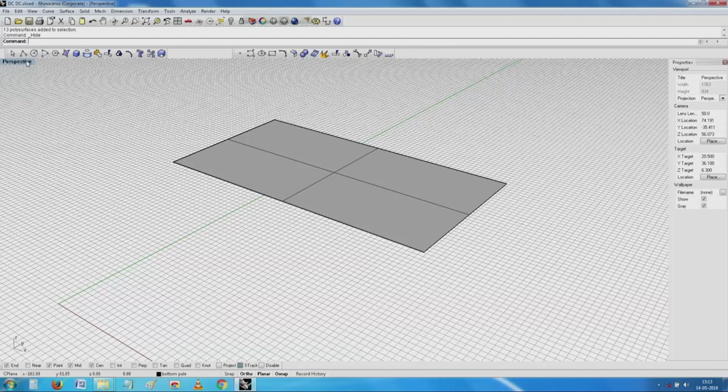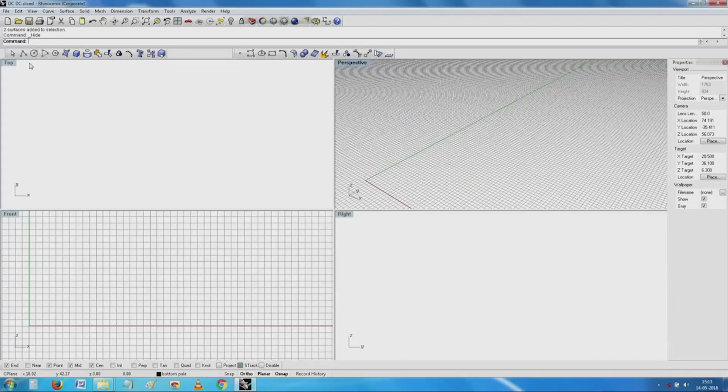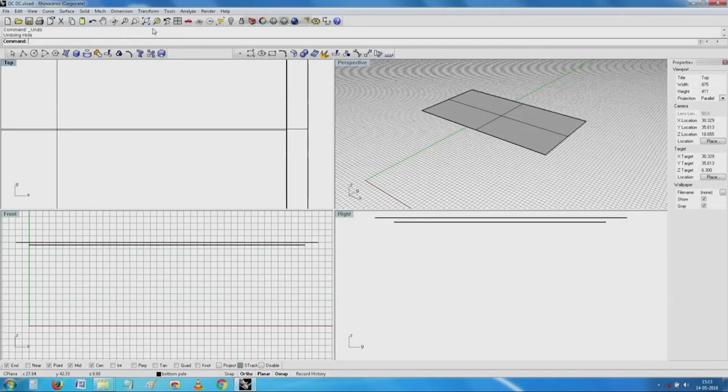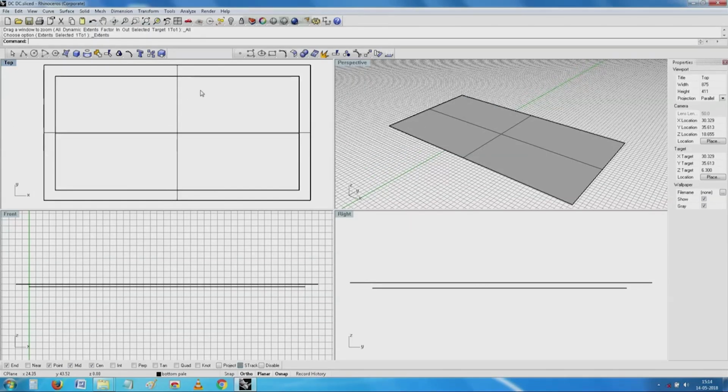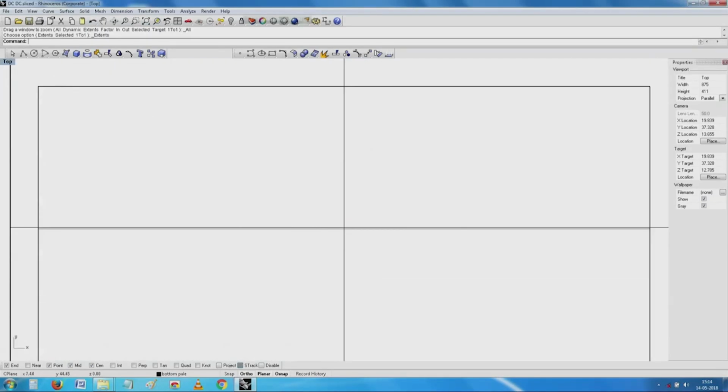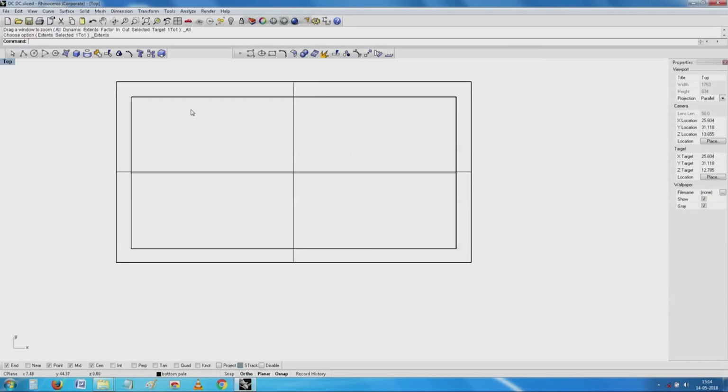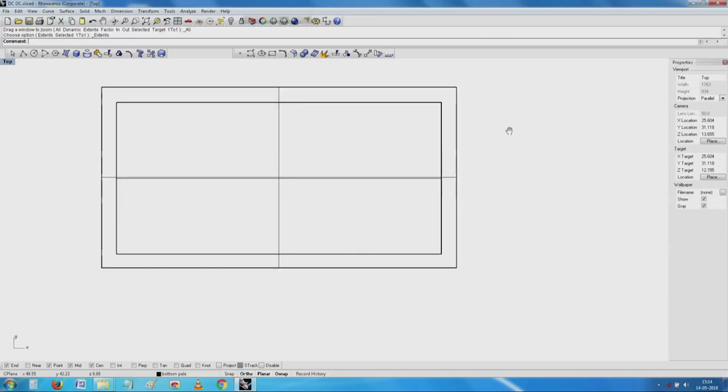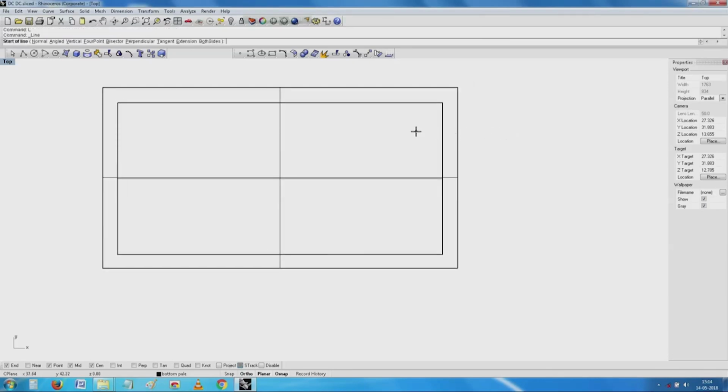Why it is useful for me to make use of it is, I come here now, I will make use of these 4 corners and see how best to avoid that shorting in the corners. So, one easy way is, because we have a notching facility, it is very convenient for us to make a notch here. All we need to do is make one more rectangle. I will go a little faster.